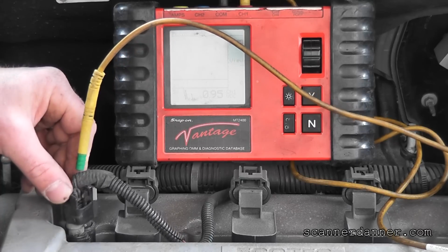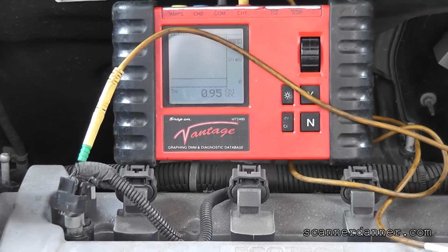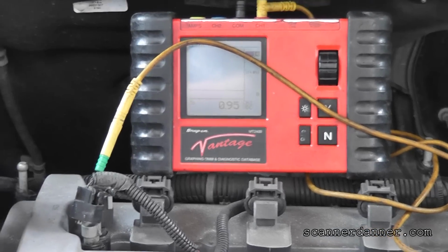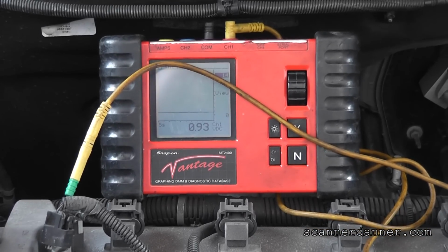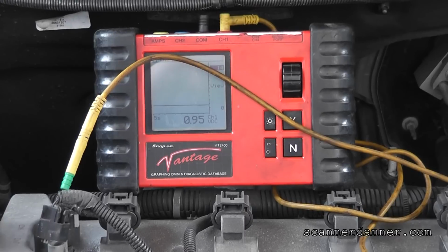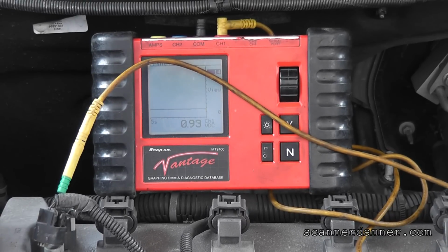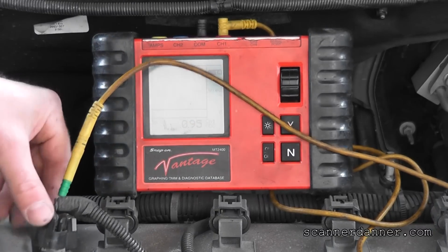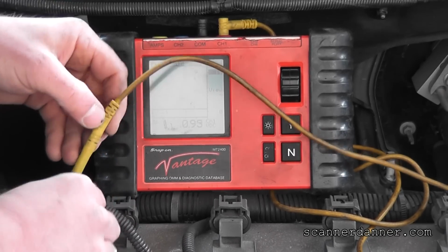It would have been nice, reviewing that flow chart that we did earlier, if the manufacturer, all they needed to do was say, hey, check for a bias voltage of 0.9 on the control wire, and that tells you the control circuit integrity is good. Not that crazy test they were telling you to do. I'm going to show you the signals anyway.